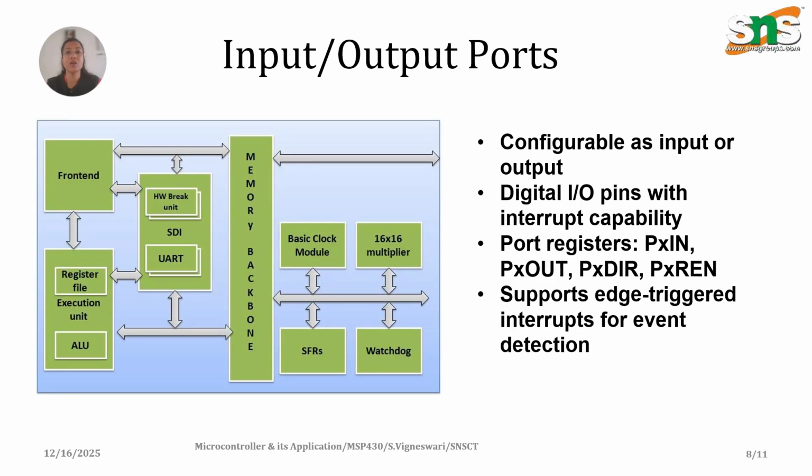Input and output ports in MSP430 are very flexible. Each pin can be configured as an input, an output, or an interrupt-enabled input. Special registers like PXDIR, PXIN, PXOUT and PXREN control the ports. This makes MSP430 ideal for event-driven systems where the microcontroller wakes up only when it is needed.